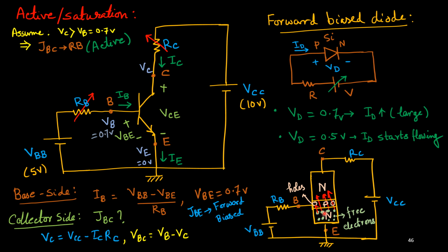Whenever these electrons move towards the collector through the base region, in the base you will find a few holes, because the base region is made of p-type semiconductor, which has positive holes. So those holes can recombine with these negative charge carrier electrons, but this region is very narrow. Thus most of the electrons will cross this barrier and enter the collector region, and once there, due to the positive terminal, those electrons are attracted toward this plus terminal and collected here. So from here electrons are emitted, and here most of those electrons are collected. Very few electrons get recombined with the holes.